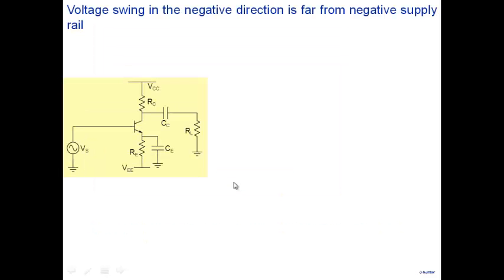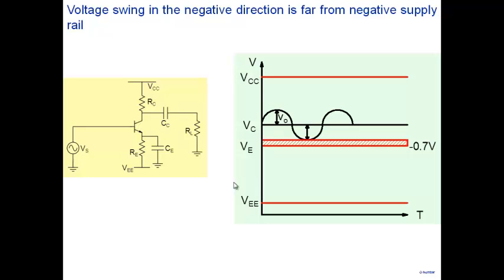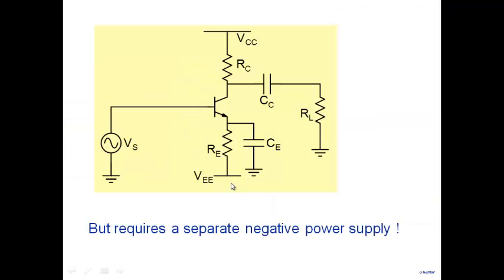And note that, in general, when you increase the supply voltage, you also want a higher swing so that you can deliver more power to the load. Because note that if I increase VCC, let's say I keep ICQ, collector current, constant, and I increase VCC. So what am I doing? The power that is drawn from the battery is ICQ times VCC. So I'm increasing the power that I'm taking from the battery here. Now that's meaningful if I can deliver more power to the load.